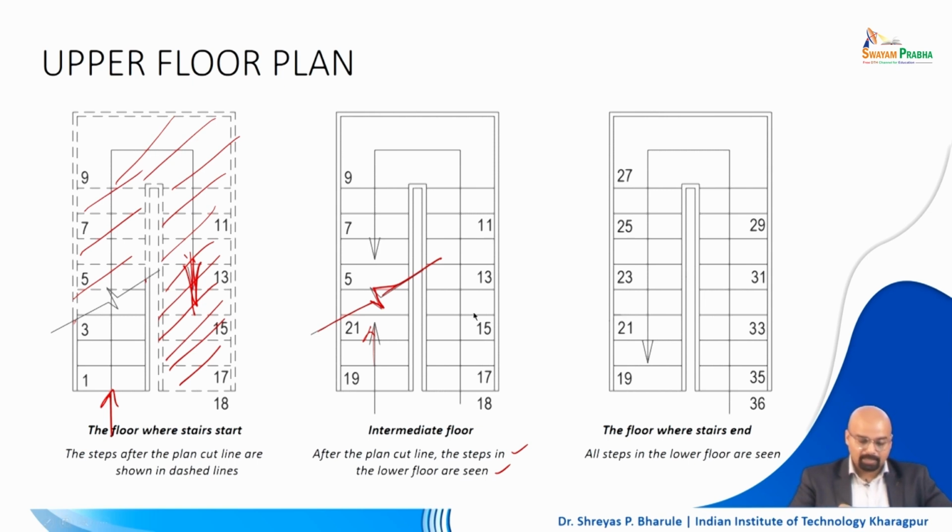But try to remember this particular situation wherein you have to observe the numbers. Here you have descending order of numbers, but there will be a staircase right on top of this from where the next flight starts, right? So the next flight would start at the mezzanine level where you come and land here. You come and land on 18, but this is the floor level which you will be using. So you will use 19, 20, 21, 22, 23, and so on and so forth on the upper floors, right? So that's the thing that you need to keep in mind when you are doing intermediary floors.